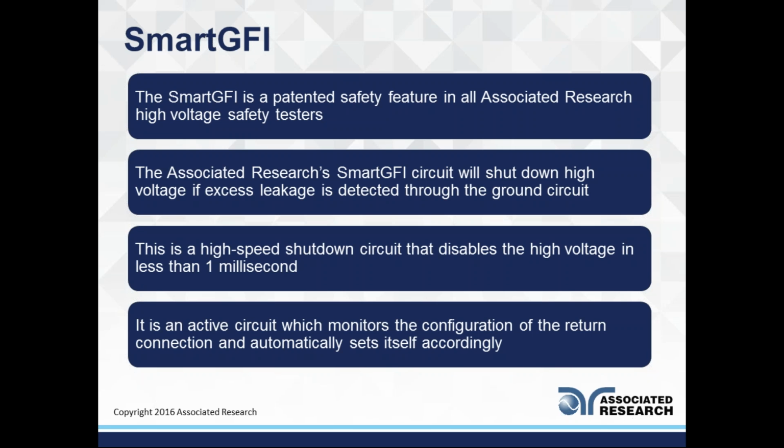So now let's get into our SmartGFI. So the SmartGFI is actually a patented safety feature in all Associated Research high voltage safety testers. Let me turn that off, sorry about that. The Associated Research SmartGFI circuit will shut down high voltage if excess leakage is detected through the ground circuit. So this is a high-speed shutdown. In less than a millisecond, high voltage will shut off or be disabled